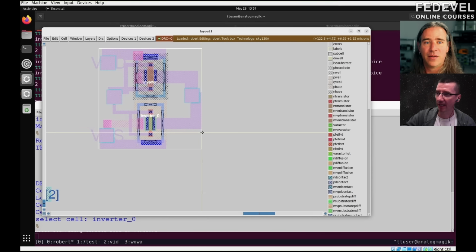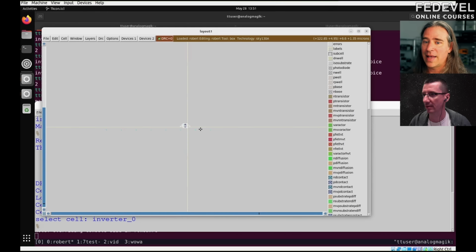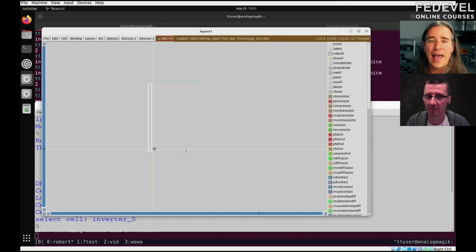Okay, so you say on the top there are digital, on the bottom analog, so where are the power rails? There are no power rails. They're basically up to you. You have to make them. And I believe the rule is it has to be 95% or more of the length of the height there, and between something and 2 micrometers.